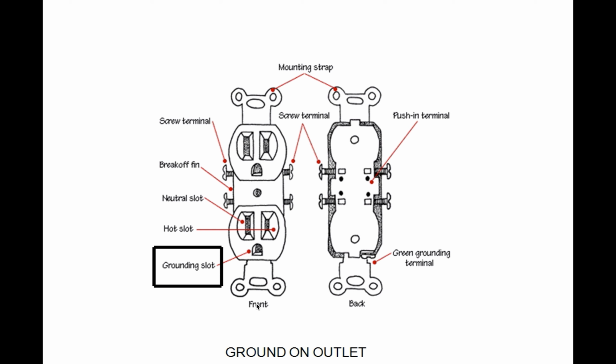Or it could be in parallel, where it terminates on the left side of this terminal, and that's the last the electricity has to travel, and there could be a number of those that then get led back into a portion I'd call downline from the receptacles here. So depending on the type of electrical system you have, both sides could be wired and could continue into another outlet down the line. So the grounding slot is the big roundish plug on the bottom, whereas you have your hot and your neutral as the two prongs that are typically on every device.